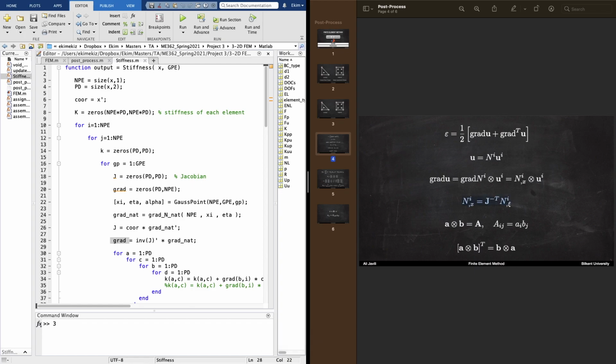And what's left to do is to take the dyadic of that thing with the displacement of every node. So again, I. So we have a summation over the node, okay? And I'm sure you have seen it already, but let's just go over it. The dyadic operation works like this. So if you have a dyad with two vectors, it will give you a tensor, a 2 by 2, a second order tensor. And it will be like this. So ai bj will be placed at aij. So you can think of i and j as placeholders.